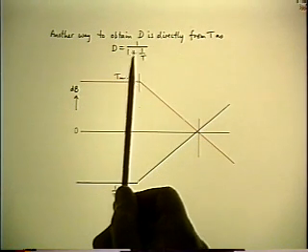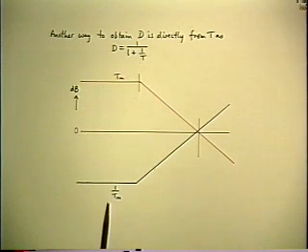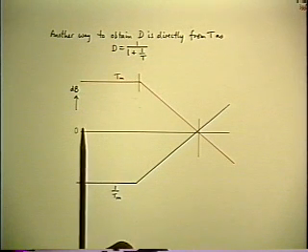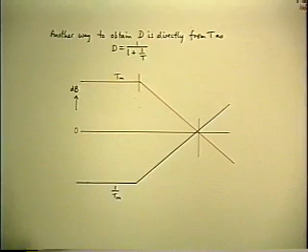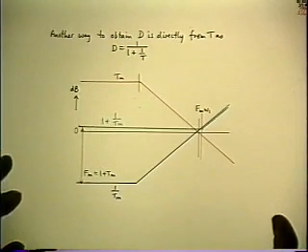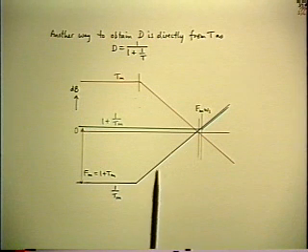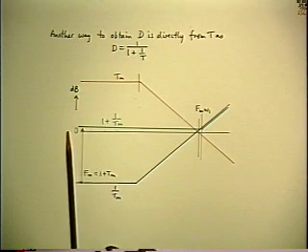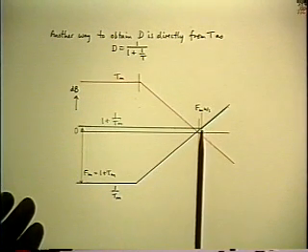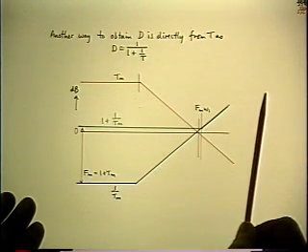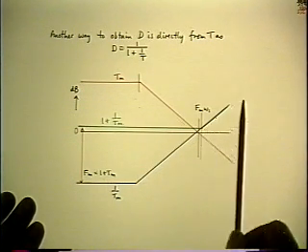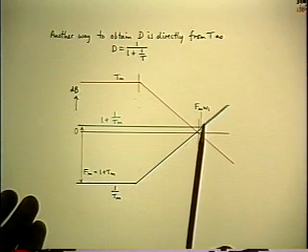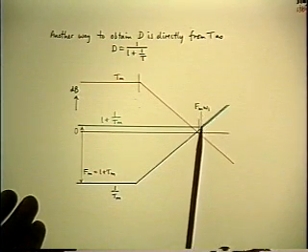The next thing I have to do is add 1. At low frequencies, 1 over T is very small. So when I add 1, the result will be just a little bit bigger than 1, or just a little bit bigger than 0 dB. And as T begins to increase, it still won't be visible. But it'll become visible when 1 over T overtakes 1. Then the sum of the two will turn around and follow the bigger one. And by gain bandwidth trade-off, the value of that frequency, again, is Fm times omega 1.